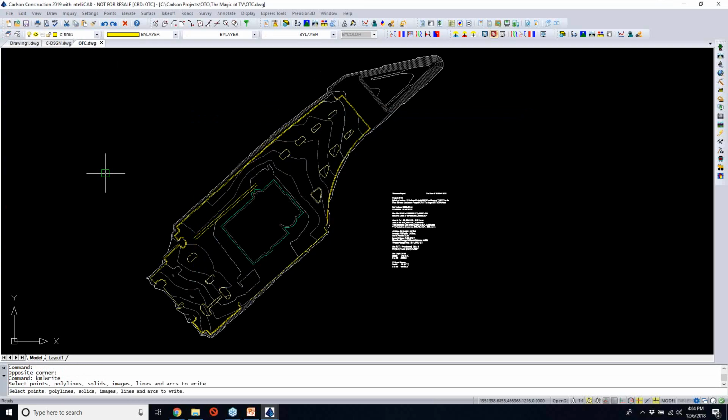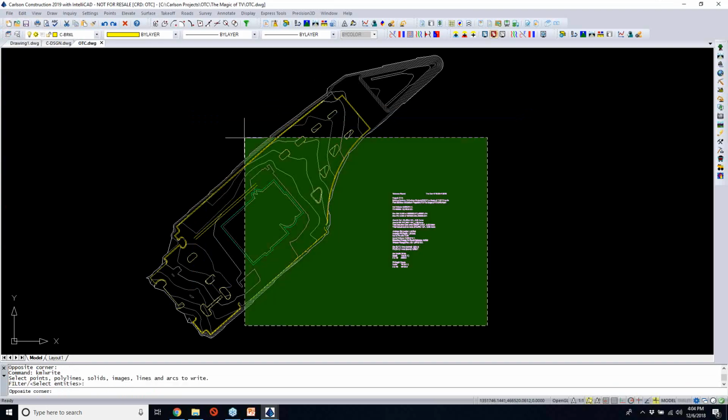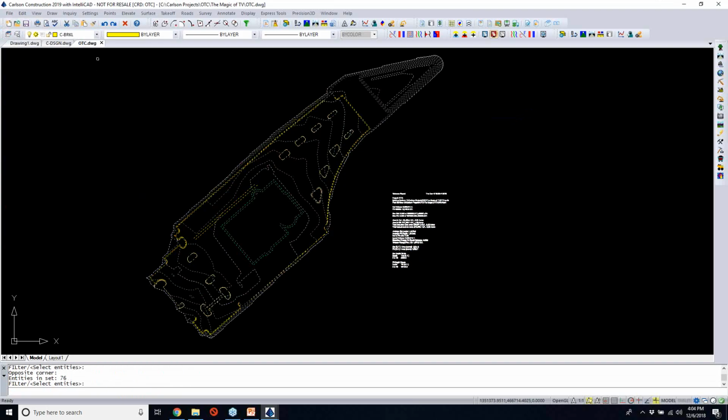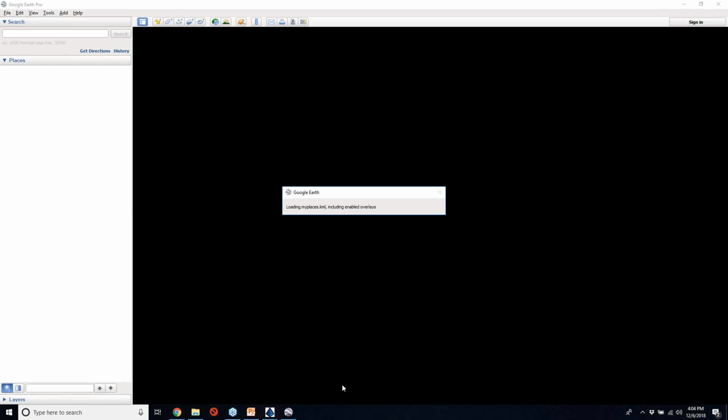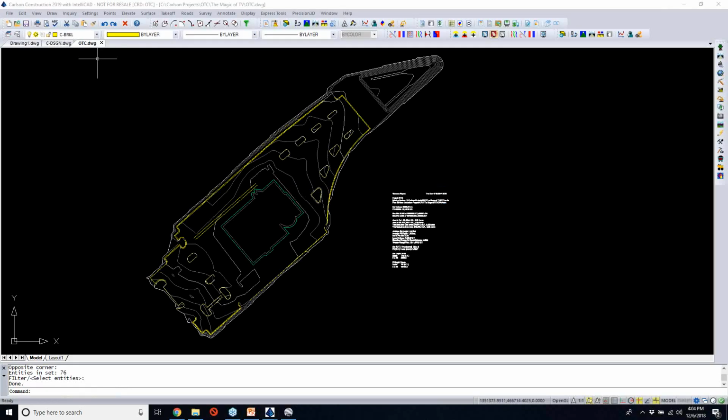And let's just put all this data right out there. Oh, and that's the other thing I probably should have done, is show you the cut fill color map. So as that's rendering out there, I'll go ahead and put that cut fill color map in there for you. That's another thing that people like to see. So if I want to quickly show that cut fill color map, we'll just go ahead and place that.